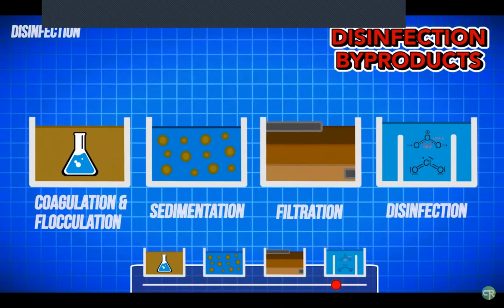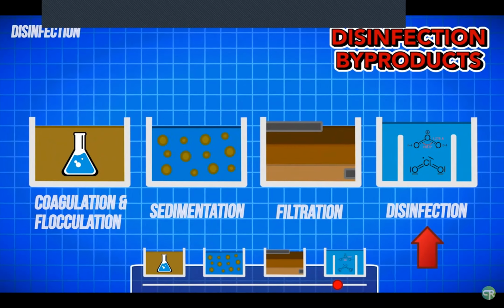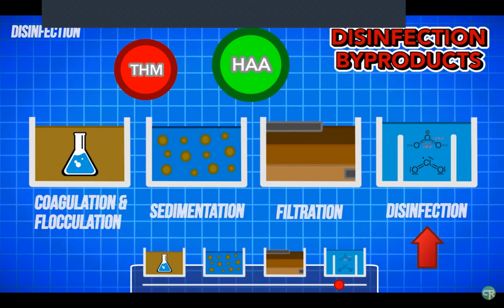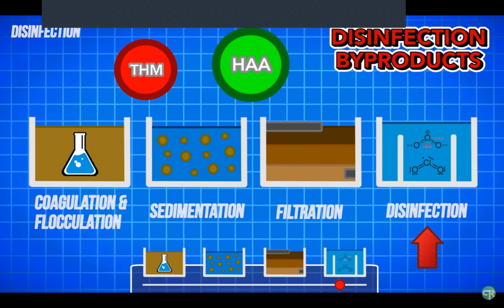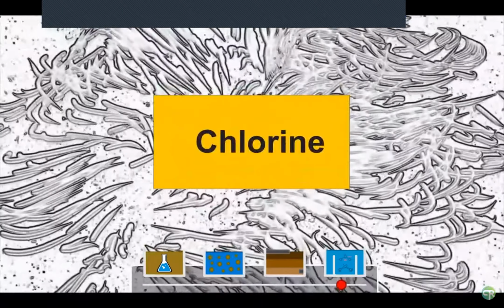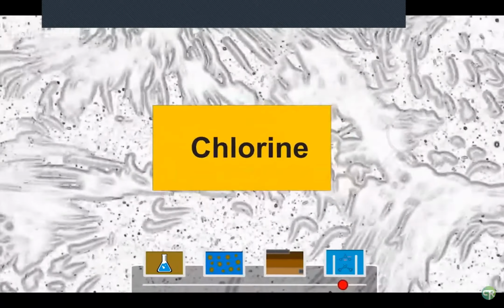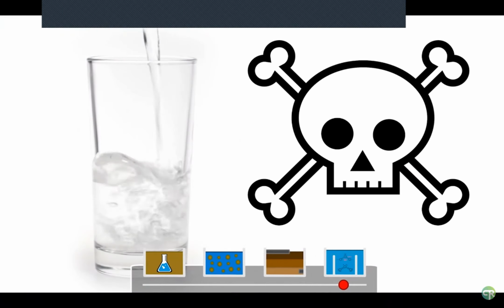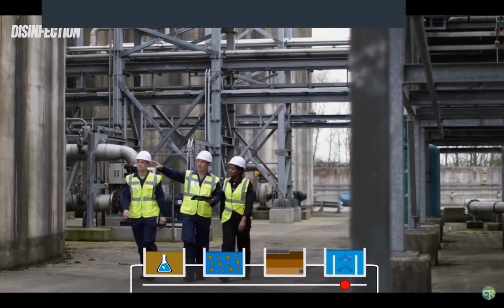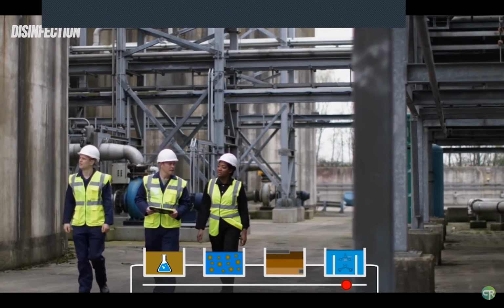This extraneous reaction with other organic material is also why chlorine disinfection must come at the end of the treatment process. If added at the beginning, an abundance of disinfection byproducts would be created, causing a plethora of issues for the engineers and plant operators. Even with all of this, chlorine is used mainly because of how it kills pathogens. It not only kills any pathogens in the water at the plant, but residual chlorine levels also remain in the tap water, killing any contaminants that might get introduced after leaving the plant. Most cities or states will have maximum or minimum chlorine levels in the treated water in order to keep both the water treated and city residents safe.